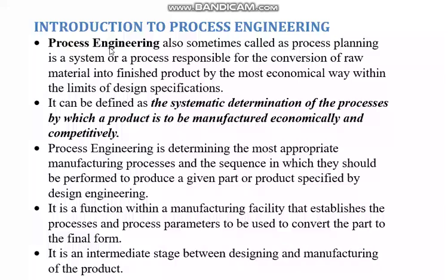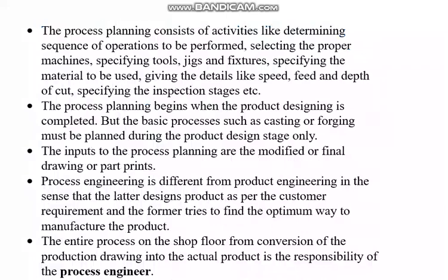Now process engineering is coming in the middle most of the times. In some product manufacturing, there may not be a clear-cut differentiation between manufacturing and process engineering, but anyway, this is a stage which comes after the design engineering. The process planning consists of activities like determining the sequence of operations to be performed.